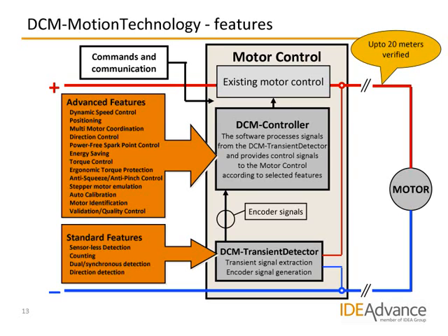during electric motor manufacturing. At the moment we are experimenting with an algorithm that can turn off the power to the motor just before the kickback transient is generated and turn it on again just after. This would reduce the arcing and therefore the brush wear. The result is an extended lifetime of the motor and power saving.